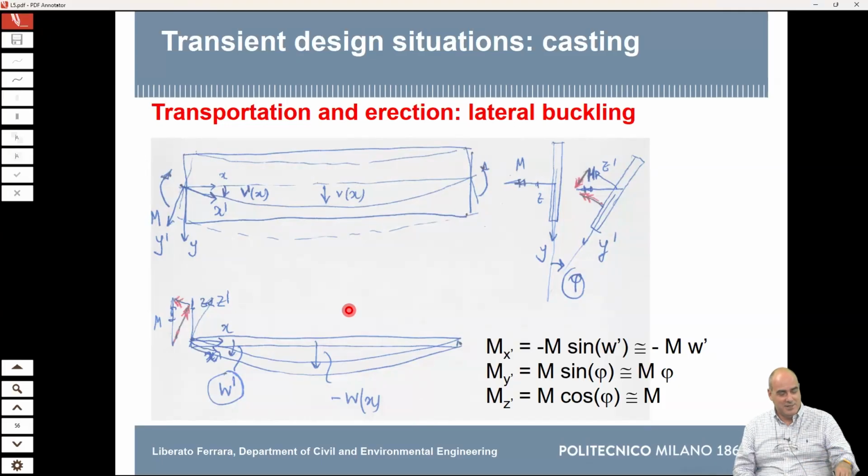He discovered buckling by hypothesizing some absurd mode of deformation to occur, and then he looked for the conditions for this deformation to occur. And you can prove this only by mathematics. Well, evidence there was: the buckling of a thin column was there. But if you consider that the column is compressed and you only apply Saint-Venant, you say the compressed column just shortens, it cannot bend outward. Euler hypothesized this.